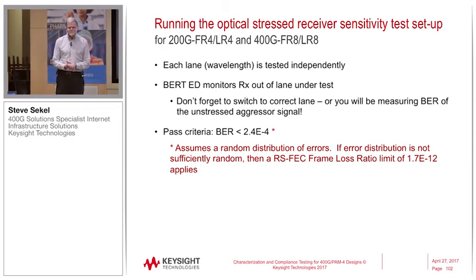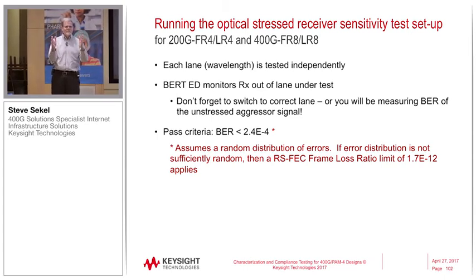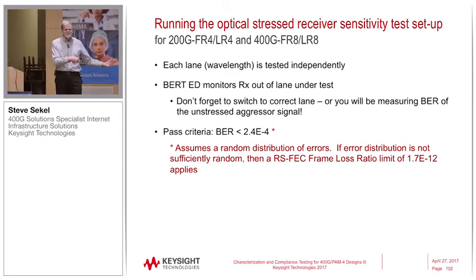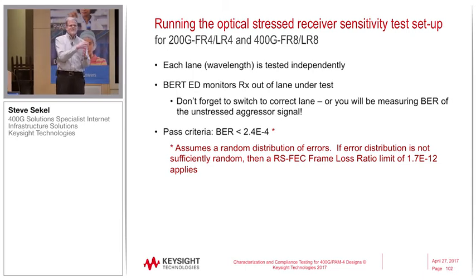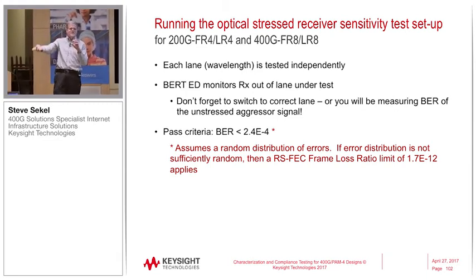And basically, you need to cascade 3 counters in the error detector. So what you do, you basically say in a Reed-Solomon frame, I have a threshold of how many errors I can correct in that frame. So the first thing you have to do is synchronize with a pattern and find out where you are in a pattern alignment, okay? Then I start a counter that counts the number of bits in that frame. And then I have another counter that's counting BER, okay? And if BER exceeded the predetermined threshold, depending on what my Reed-Solomon algorithm is, then that's a frame loss. So if I exceed that number of errors within that Reed-Solomon frame, the entire frame is non-recoverable. Okay, but that's a third counter that just gets an increment.